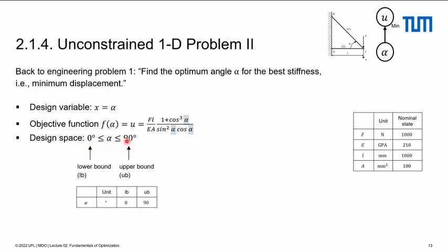what we did here is we said we're going to restrict our design space to 0 to 90 degrees. And there's one thing missing here, though, because the absolute values should be in here anyway. Can you just take a brief note for the correction, because the absolute values here are missing? So even if you restrict your model, and that's another thing I wanted to mention, if you restrict your design domain and you're safe, you still want to use the fixed model. If you're working in a team with other people and they don't know that your model only works in that design space, you don't want to leave landmines hidden in your model. That's why there should be absolute values here too.